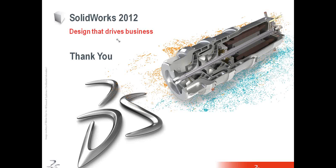If you do not want to highlight the change in dimensions, what needs to be done? This is from Mr. Kumar. Okay. Basically, you have options. You have an option of controlling it. If you don't want to highlight the change in dimensions, you can always do that. All you have to do is go to options, drawing options, and then you have a checkbox there which you can uncheck in order to take it off.